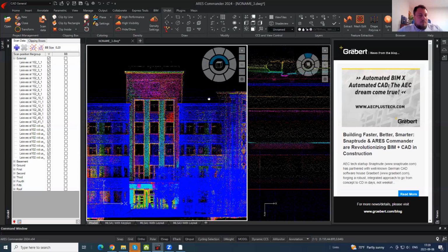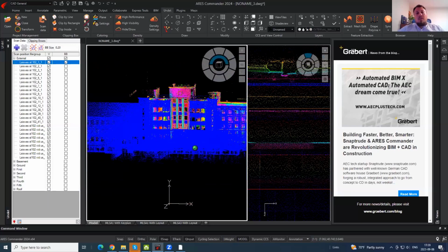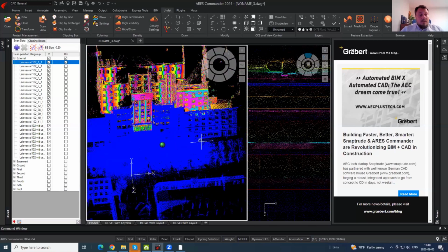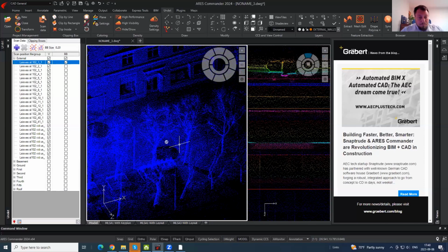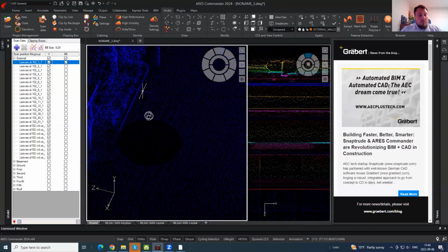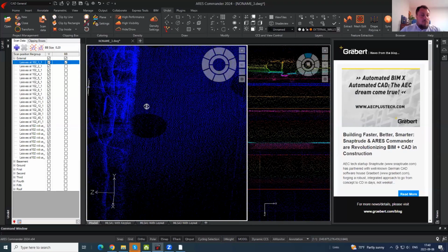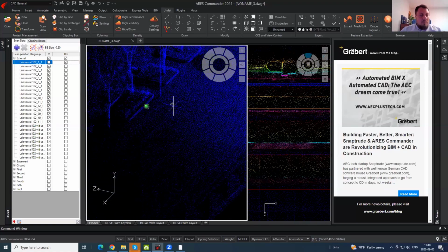Just look, all the scan station names are listed here, and you can deactivate and rename those names. Whatever files you import, you will find in the scan data window, and that is the benefit of our live data structure. If all the files are not merged together, then you can manage the visibility of each group or individual files. And even, as Darius showed us, for example, if you're working with the elevation view, you need to deactivate internal scans because there are some reflections.